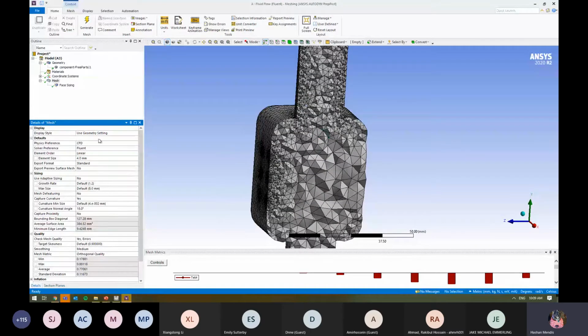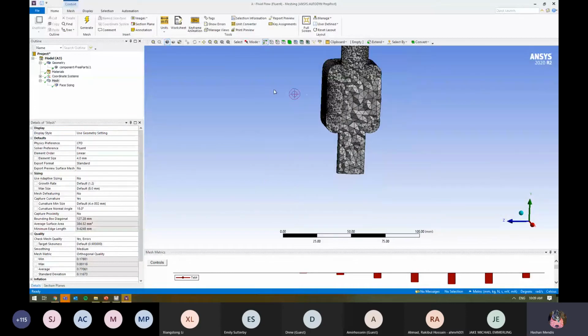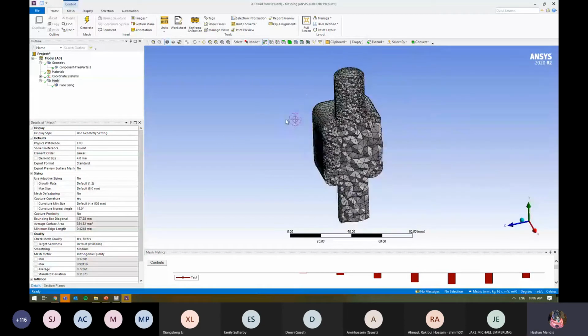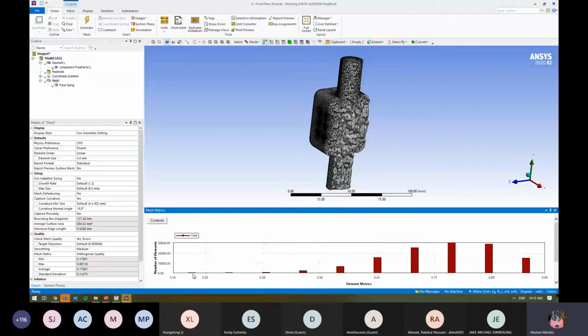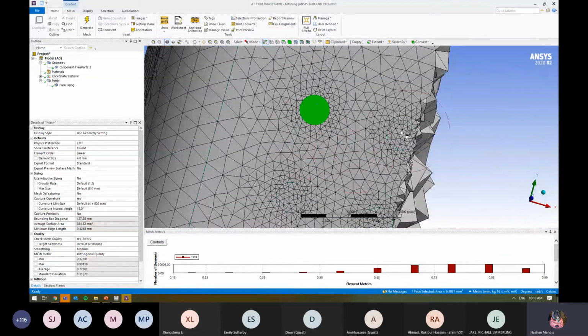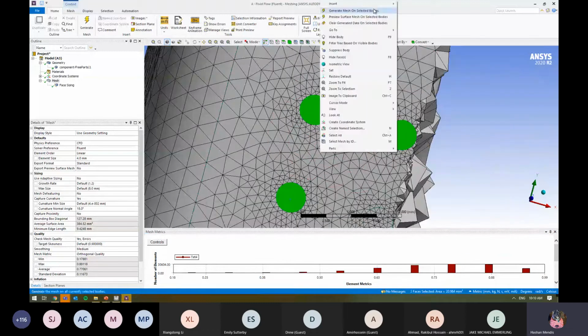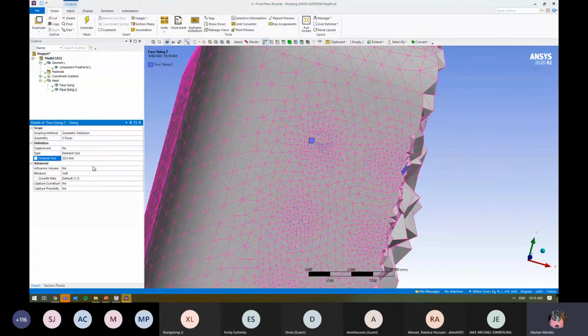It's still at the 4 millimeter level that we specified before. If there are any problem elements, I might identify where we've got problems around here, and then implement local sizings around some of those regions as well.